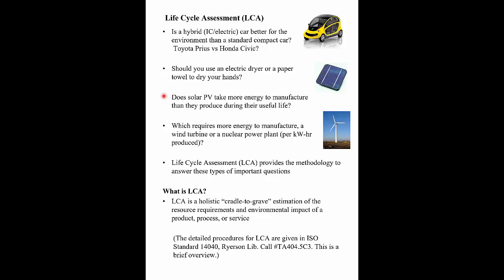Another issue that I think I raised in the photovoltaic section is solar panels. So solar panels like this single cell panel here, does it take more energy to manufacture than it produces over its useful lifetime? Well, you should know the answer to that. I discussed it in that presentation. The answer is no. If you're in a not very sunny location, it takes about 7 years, and then you can go down to as low as 3 years in a sunny location for a PV panel to pay back. And the lifetime of a PV panel is 30 years. But that's how you would answer that sort of question through life cycle assessment.